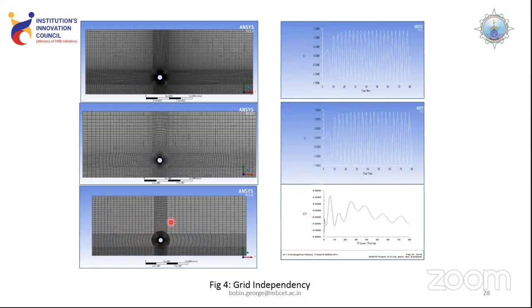For this arrangement, I am getting a variation in lift with respect to the cycle time in an oscillating manner. Moving to my second grid, I made the grid much coarser compared to this. Over here, the mesh generated is much simpler. That means the coefficient of lift generated over here, instead of this oscillation, tends to come near a linear manner.